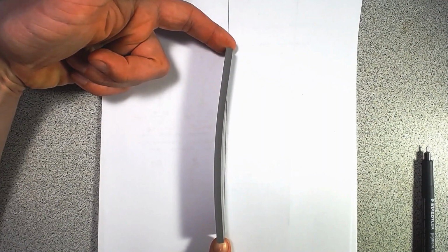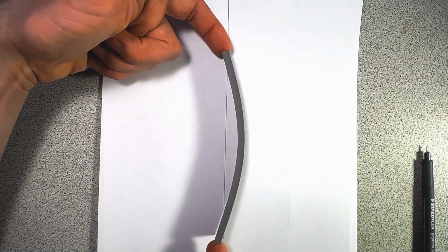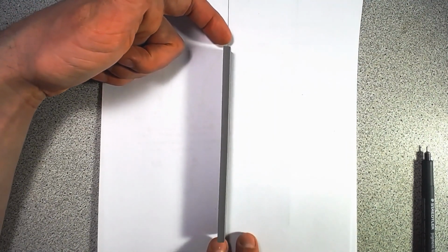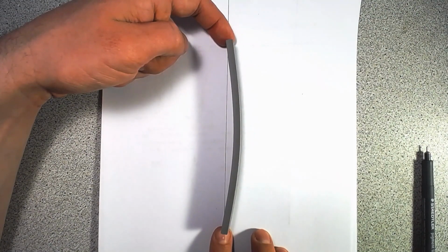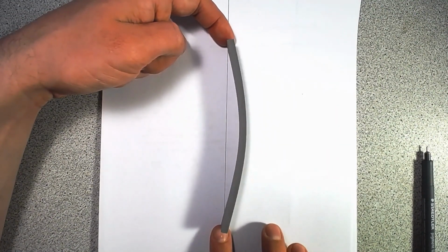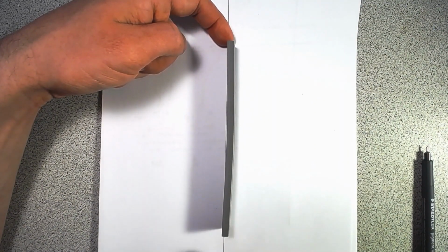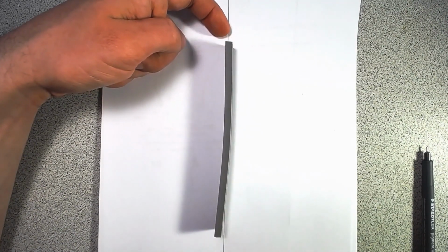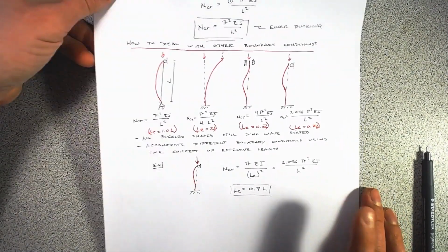So if we work really hard to line up, we can get it to take a significant buckling load. But for example, if we start with a little bit of out of plane movement, it's actually quite easy to buckle. So once something has started, even with this really small out of plane movement, it's really easy to buckle. Now, why is this important for design? Well, that's because real columns aren't straight, and so they have some initial out of straightness.